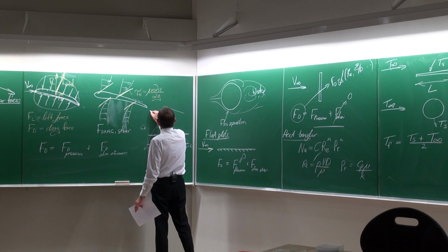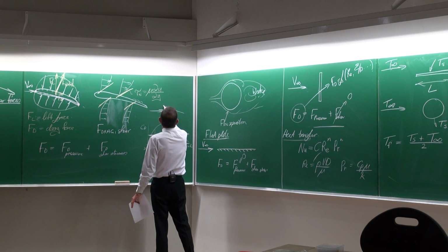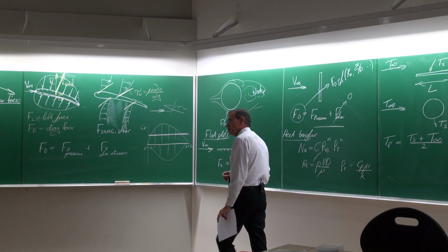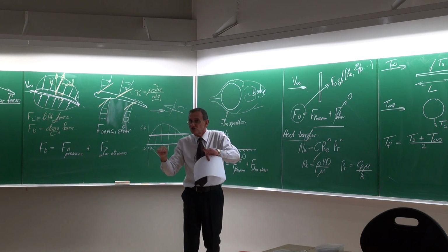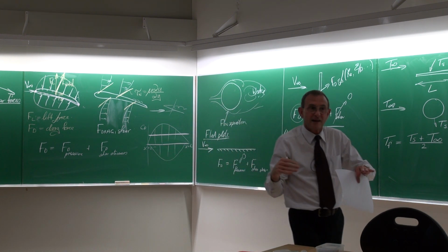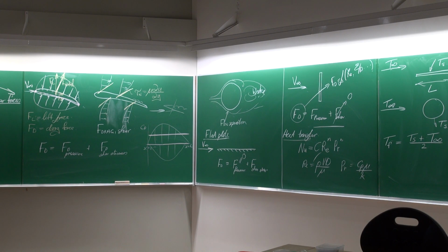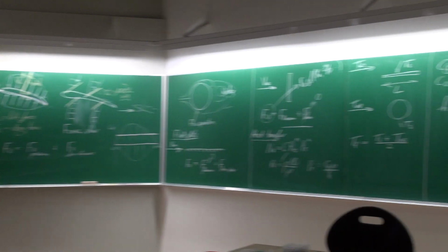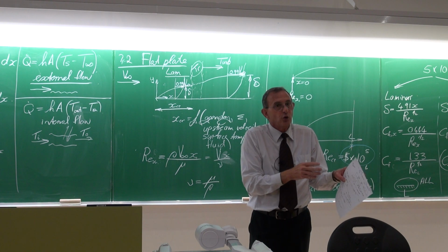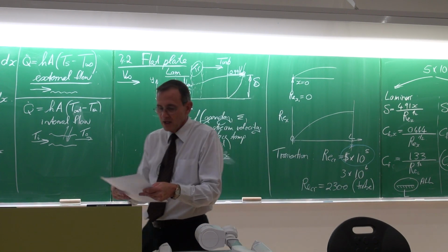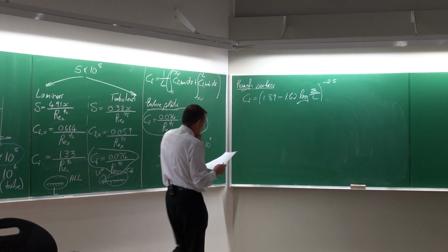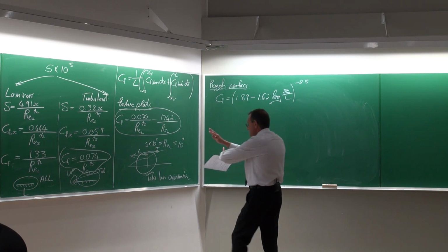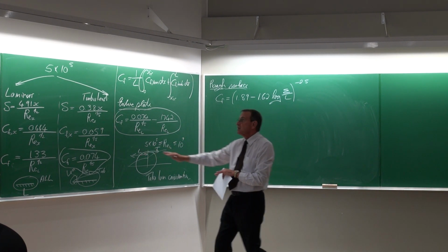If there's an angle of attack, typically like that, then the boundary layer will grow, but then at some stage we will have some flow separation. And this flow separation can actually be controlled by changing the surface roughness. By making the surface rougher, you can actually prevent the flow from separating at an earlier point; you can move it downstream. So a lot of work has been done also on this for different types of geometries. Now that is a summary of the fluid mechanics part.